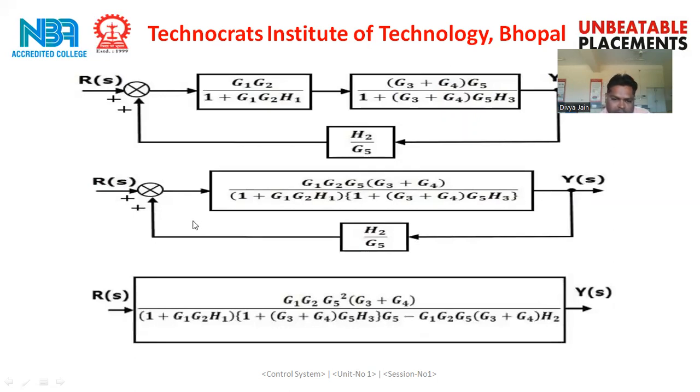And in this block diagram, this is the forward path and this is the feedback path. Again, this is the closed loop path. So the result will be the forward path divided by 1 plus, this is the plus sign. So the result will be the minus. So 1 plus or 1 minus forward path multiplied by feedback path. So it is the overall transfer function, output to input.